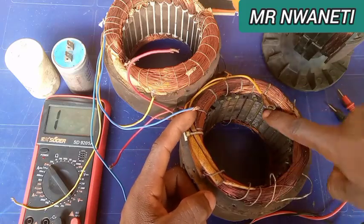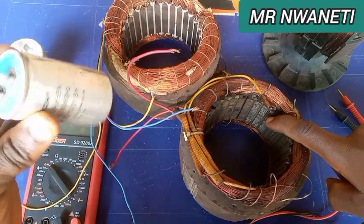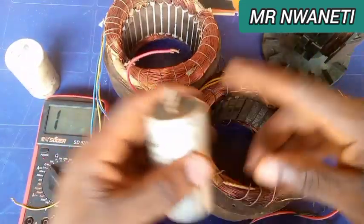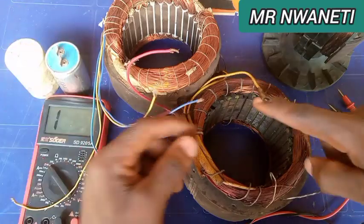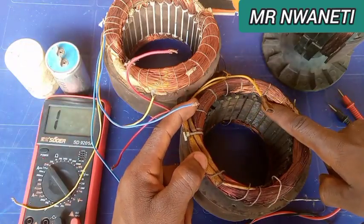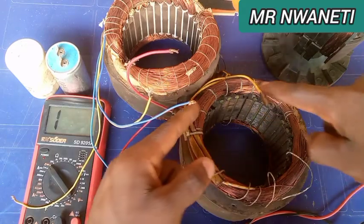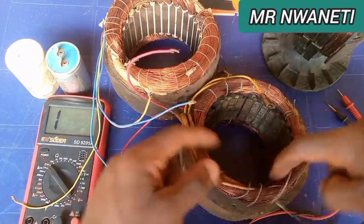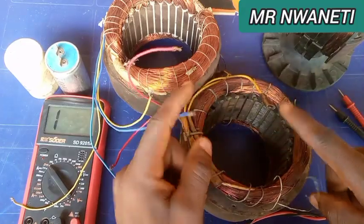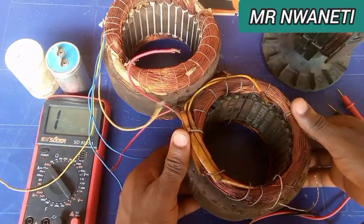Adding more turns here may result in putting a smaller value of capacitor, and when you put a load it will be fluctuating, so everything has to be calculated. You have to make it accurate. Just add a few turns, monitor it, then if it doesn't give you what you expected, add more, because this is electromagnetic, dealing with electromagnetic flux and other things. So it varies, even one turn can vary it. So you have to be careful when you're doing so.